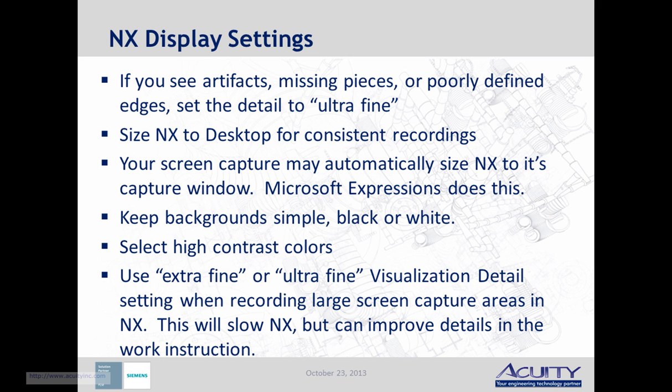For colors on your models, select high contrast colors. Use the whole color wheel. So red, blue, green, yellow. They're easy to distinguish and make for good instructions. And use extra fine or ultra fine on visualization detail when you see the edges of things are polygonized.